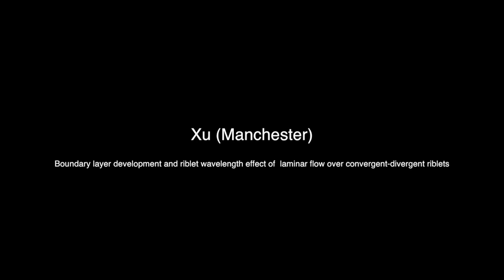So this is our experimental facility, just the schematic of the stereo PIV. We apply dye visualization, mono PIV and stereo PIV to explore the flow field. In my report, I will give the micro and large-scale vortical structures, and try to understand the flow topology. Later on, I will show its impact on the vortical structures and the velocity field, and also investigate the riblet wavelength, because it's a really important parameter of our texture.